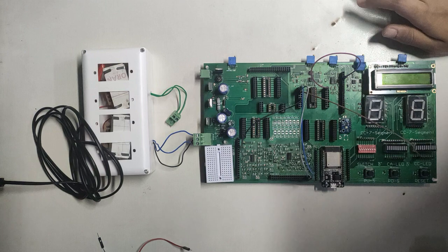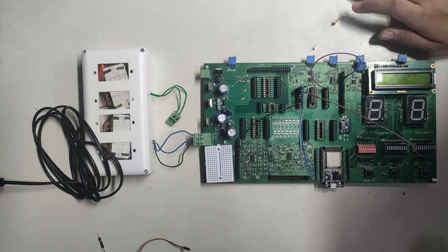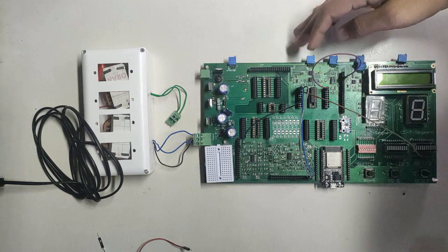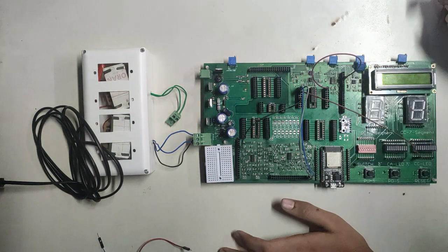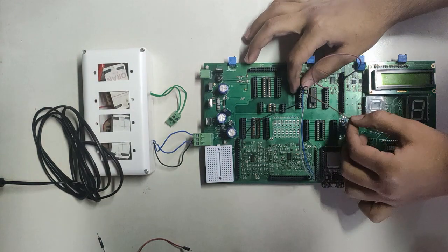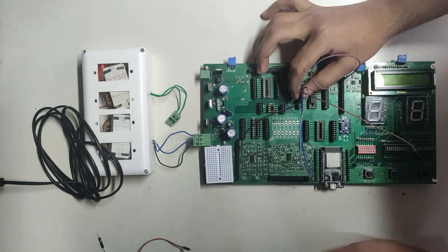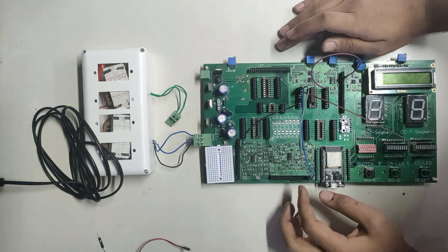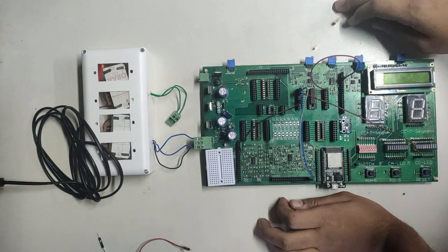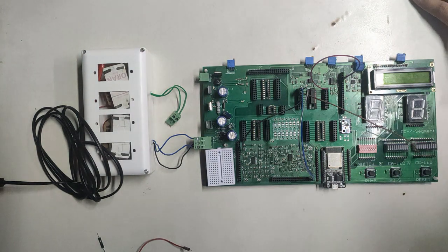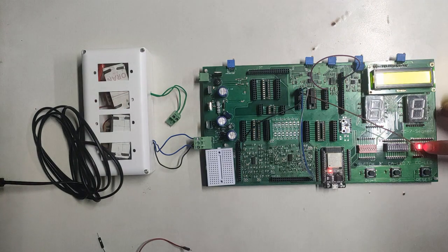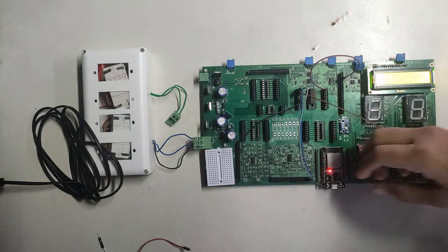After inserting the IC, this is how the circuit looks. By referring to the pin diagram, pin number 14 is again VCC and pin number 7 is ground. Now let us verify the truth table for the NAND gate. Pin number 1 and pin number 2 are the inputs and pin number 3 is the output. Both the inputs are connected to the ground, which is logic 0. If the inputs are logic 0, 0, then the output must be 1. Let us verify that. Here the LED is glowing, so we can say that the output is logic 1.